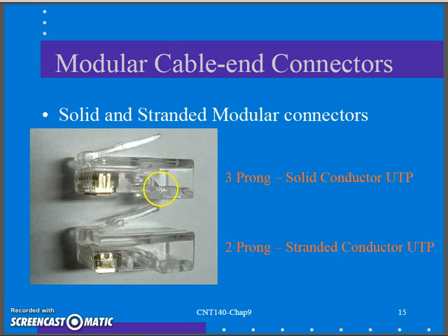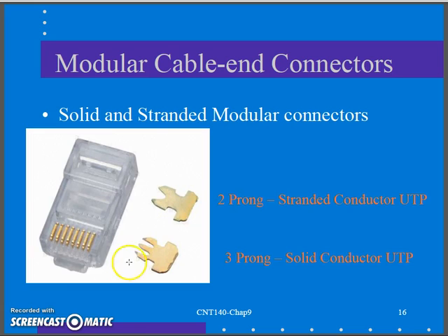If I see a modular 8-pin connector with 3 prongs in there, that is typically designed for solid conductor UTP. Again, we're not going to use those in our lab, and we're not going to terminate patch cables with solid conductor, but they do exist. They are out there. Meanwhile, if you see a modular 8-pin connector with 2 prongs in, this is really designed for stranded conductor. I have a couple more pictures to show you.